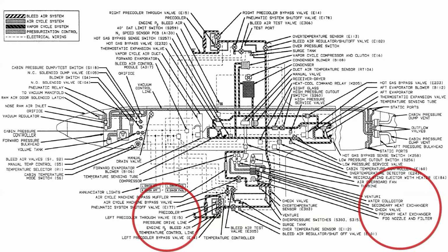A heat exchanger and two valves on each engine pre-cool the bleed air, which has been heated to around 200 degrees Celsius. Bleed air is also expanded to bring it to cabin pressure.